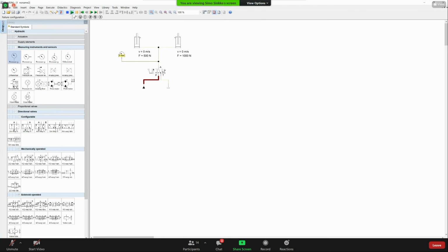So they come back so quickly that you don't see the difference. But the point was that if we have some unbalance in our load, always the oil goes where it can go the easiest way, because this left cylinder needs less pressure than the right cylinder, and the pump generates only that amount of pressure what is needed here.